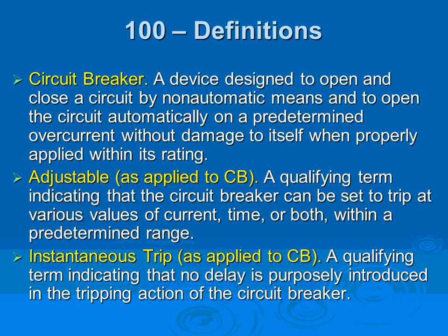That's your adjustable circuit breaker explained by an engineer. I'm sure a lot of you have seen adjustable breakers around, but that's how, when you work in a hospital and you have to do overcurrent coordination, the engineers do it. You grab all these curves, and as long as they don't touch each other, you're good to go. If they overlap and touch each other, it means a ground fault in this panel will trip a 1200 amp switchboard. Is that good, bad, or ugly? That's ugly, especially if you're in charge. So that's your adjustable circuit breaker.